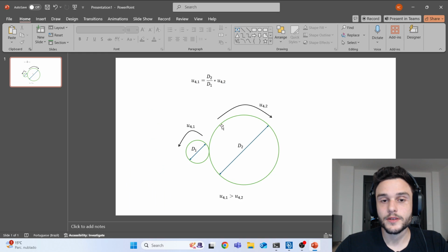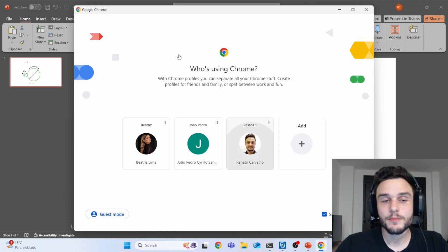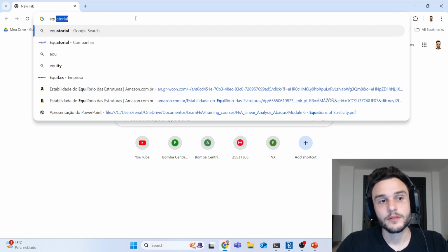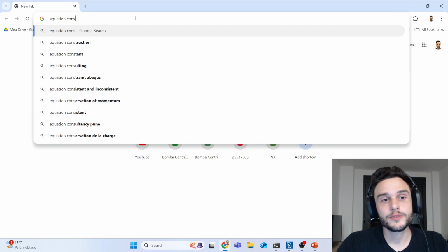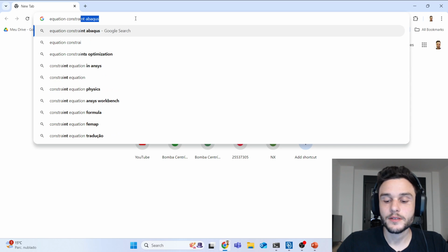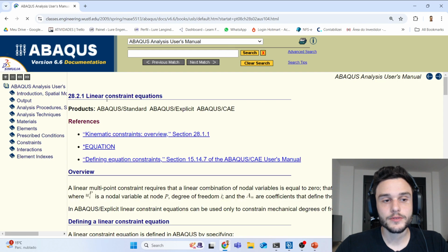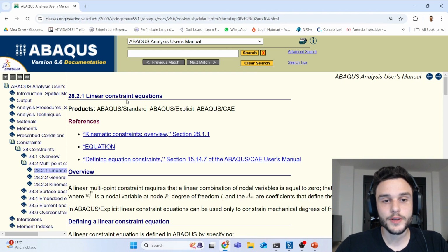Okay, so how do we tell this software about this relationship? We are going to use something very interesting, that is equation constraint Abaqus. Let's click on this first link, linear constraint equations.